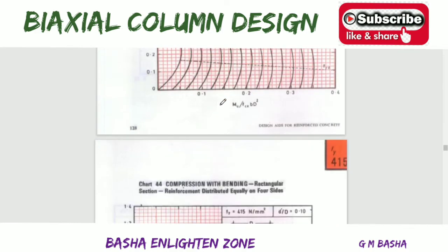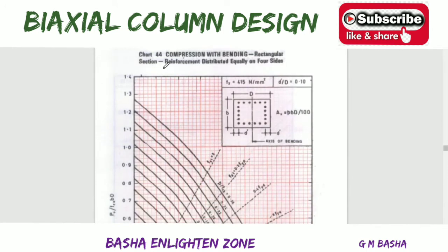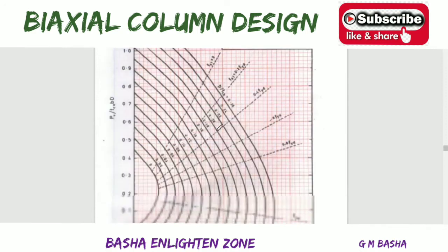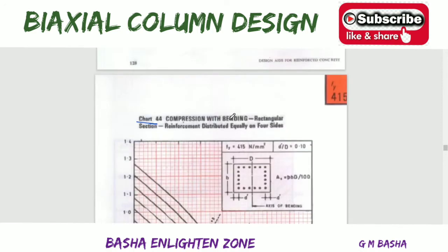So see this graph, which is chart number 44. In this chart number 44, which is page number 129 in your SP16, it is better to note down 129. Okay, so this graph is related to d dash by d equal to 0.10 and Fy equal to 415 Newton per mm square, and the reinforcement also equal on all sides.